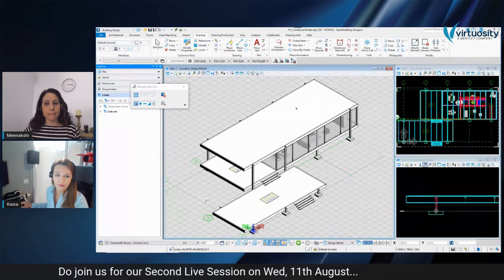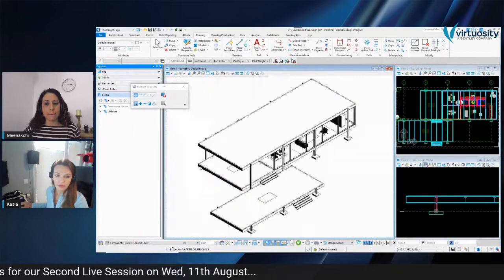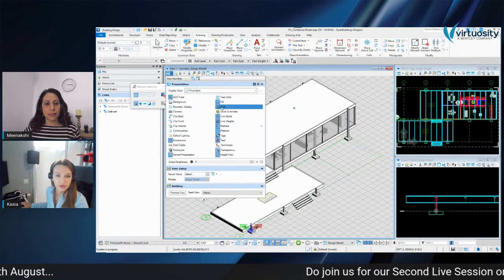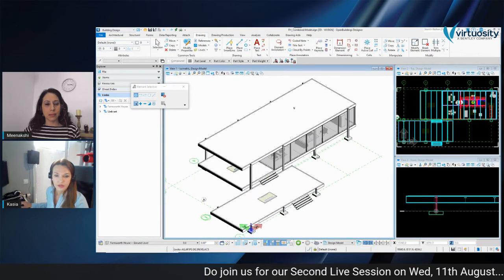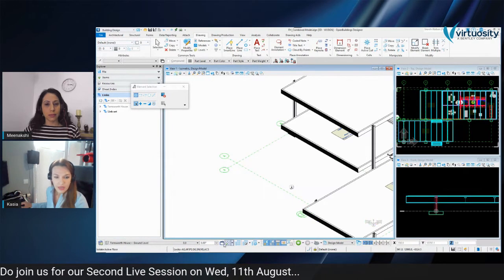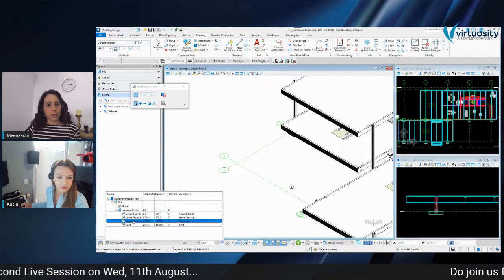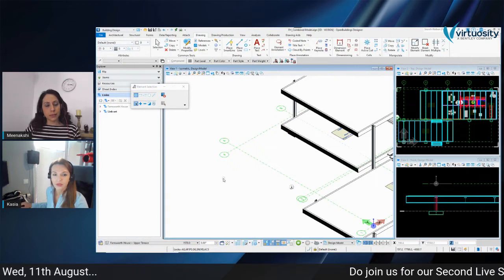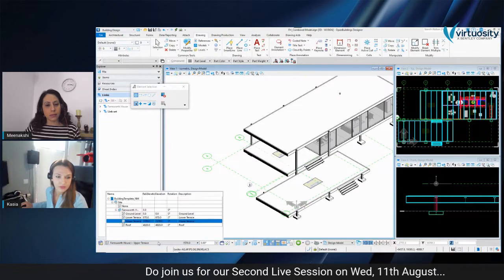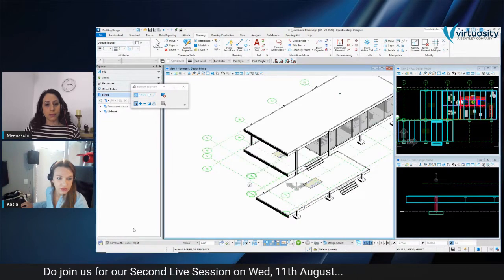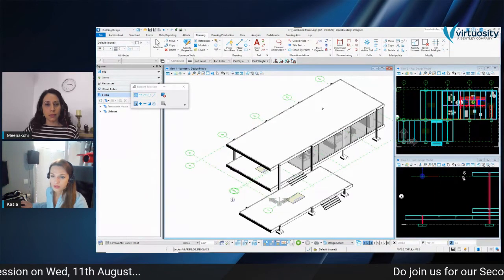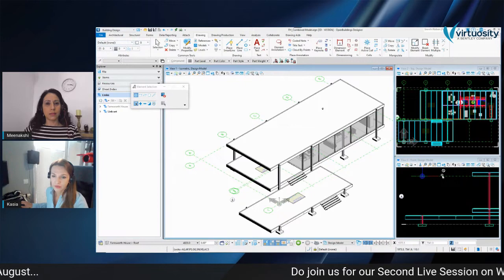So the ground floor. And I can also switch off this additional grid in the view attributes here, just to make our structural grid that we created more visible. And when we change the level in the floor selector, the grid is moving according to what we selected. Here in the upper terrace, it's almost in the same place. So let me choose this one, and you can see the active plane went to the other floor.